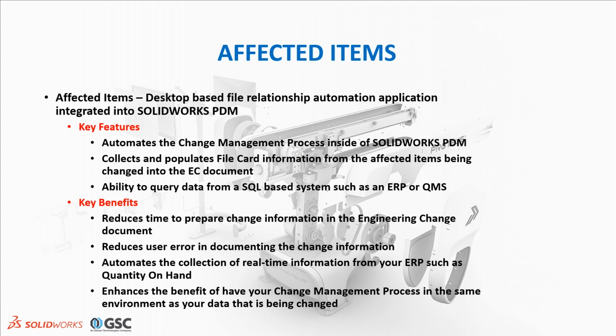The fourth and final application that we're going to look at today is the Affected Items app. The Affected Items app is a desktop-based file relationship automation application that is integrated into SOLIDWORKS PDM Professional. It automates the attachment of affected items to your EC document inside of SOLIDWORKS PDM. It collects and populates that file card information from the affected items and automatically displays that in the EC document. It also has the ability to query data from a SQL database and pull that information into the change notice.